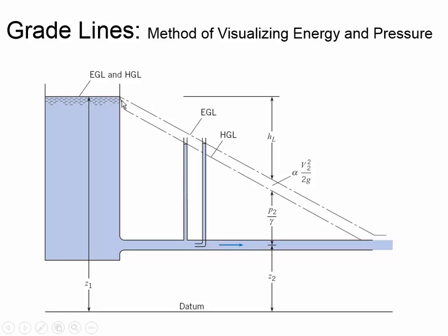There's a little bit of a line here where it's extra steep. And what that part of it means, it's just trying to show that when you have the water here before the opening of the pipe compared to inside the pipe, there's some difference because the energy in the water here, you have some elevation and then you have some pressure. But then the water that's inside of the pipe, you still have elevation above the datum and there's still some pressure, but also now you have velocity head.